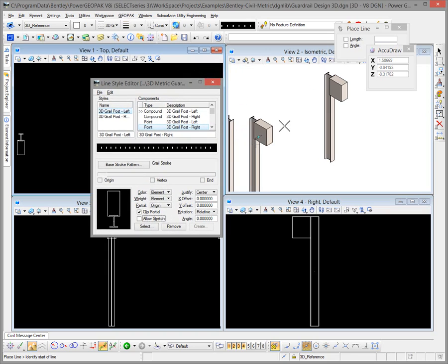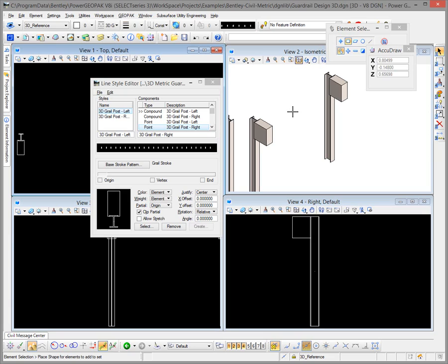One thing to just point out here real quickly, you don't have your material assignments showing up over here like we had set that up. There is right now a restriction with just MicroStation in general, where material assignments on solids for 3D custom line styles are not going to show up. I don't think that it should keep you from setting them up properly, but you would have to actually drop the line styles and use things like Luxology to get that material in there properly for a finalized model. But just so that you understand that that's why they don't show up even though we set them up. Hopefully eventually we'll get that enhancement in there.